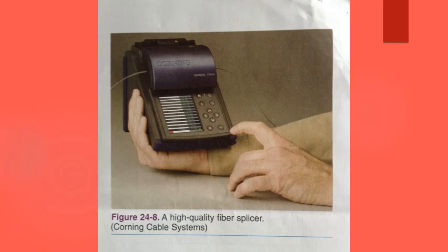Plastic core cables need not be cleaved, but an extremely sharp cutter must be used to obtain a clean, clear cut. Marks or scratches on the ends of the core material will result in a tremendous loss of light signal due to the reflection and refraction. The light will scatter in many different directions rather than transfer directly to the next cable or connector.